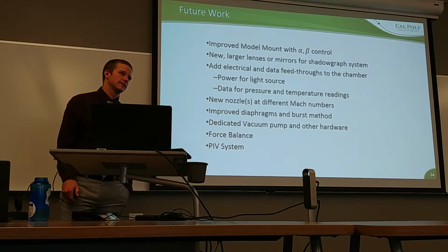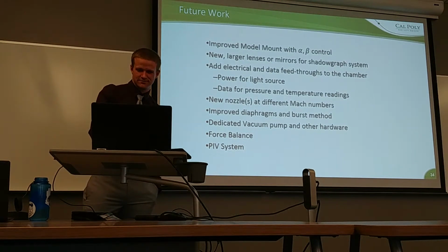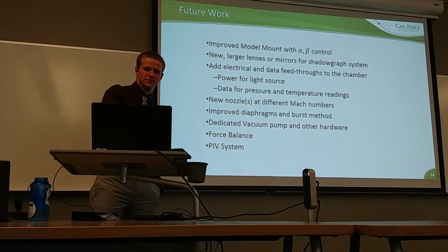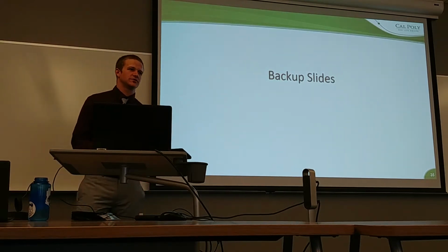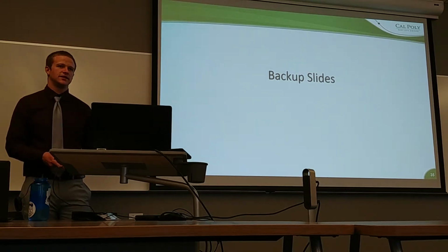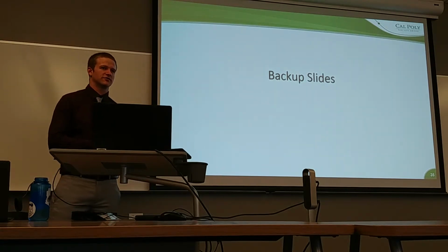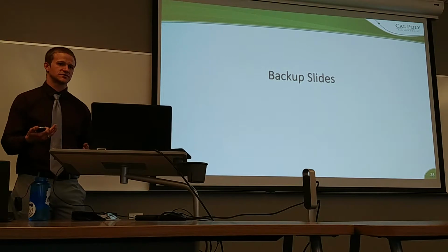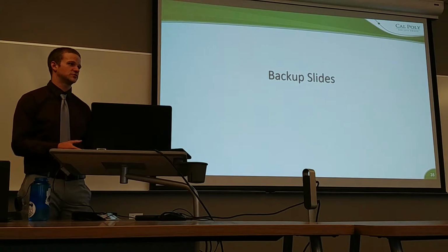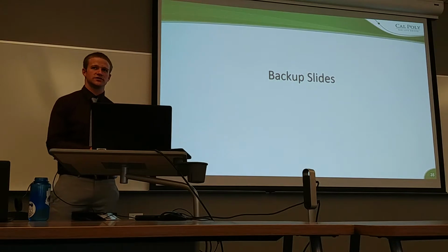What's the lowest pressure achievable, and how long does it take to turn around the test at 25 torr? That's a good question. Oh no, I didn't include it. So the question, Damon, was what's the lowest pressure achievable by the chamber, and how long does it take to turn around a test? We did a full pressure test where we stacked a number of diaphragms onto the inlet to make sure it wouldn't burst or slip out, and then ran the vacuum pump for 2 hours to see what pressure was attainable. We got to 1.5 torr, and it took about 2 hours to reach that pressure.